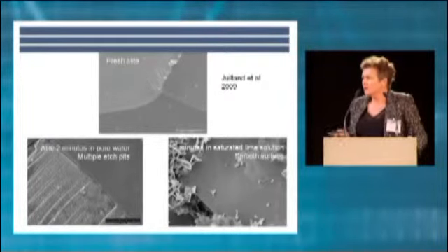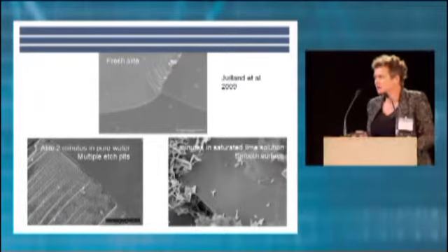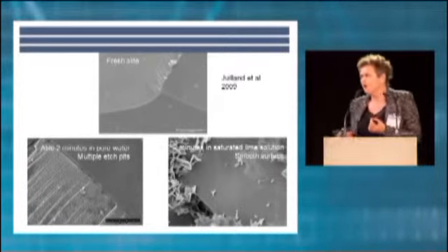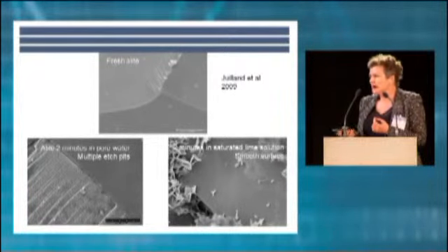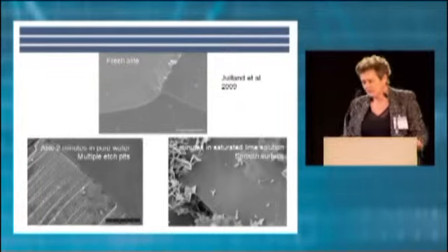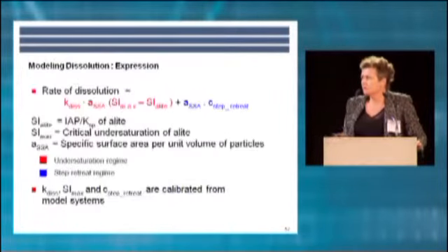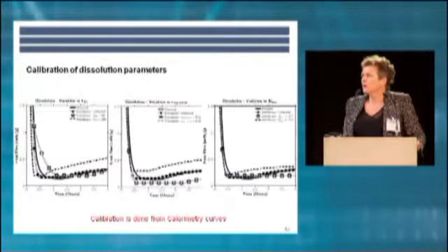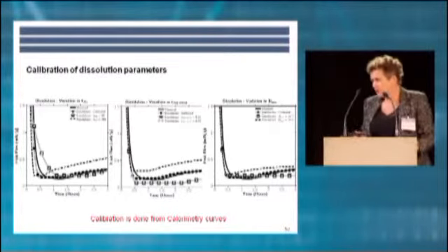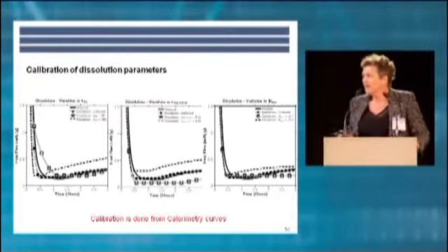On the other hand, once the solution becomes saturated with calcium, if we have a saturated lime solution, this is already enough to drastically slow down this reaction, so we don't get this formation of edge pits. And by understanding this process, we can then represent it mathematically, we can fit the parameters according to the experimental detail, and we can really capture what is happening in our materials.